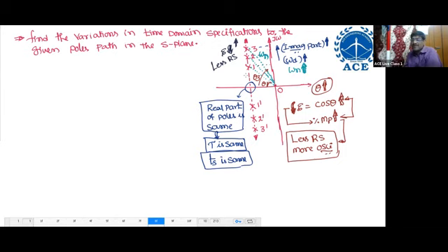That is wrong. The RH criteria never gives the pole locations, and it cannot give the exact relative stability, only an approximate one. For exact relative stability, we should know the real part as well as the imaginary part of the pole. With the real part the same and the imaginary part increasing, the relative stability of the system decreases.